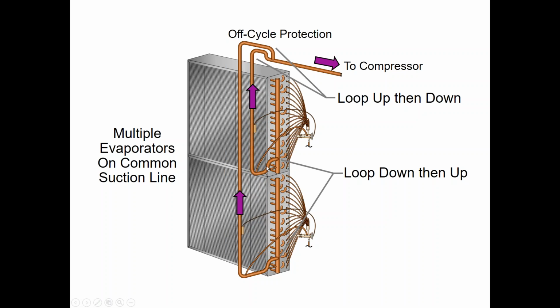Well, when we have that, this is how you combine it. We combine the circuit on the bottom and the circuit on the top. In a row split coil, meaning if we drew a line right down through the middle of the coil like this, that would be row split. In that case, the leaving side of the coil circuit, which would be this side, because airflow is going this way, would be your first on, last off circuit, for the same reason, condensation management. If you brought the air entering side of the coil on first, then think about that. We're generating our condensation back here. As air travels through, we carry the condensation through, it gets to the warm side of the coil, and it just spits off. We don't hold on to it.